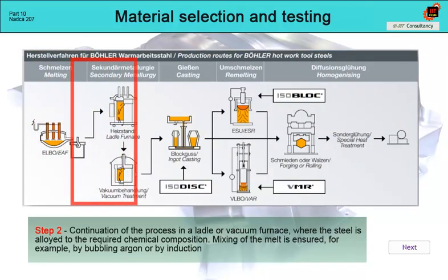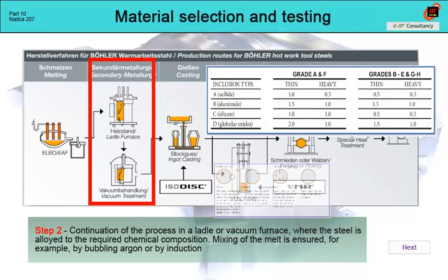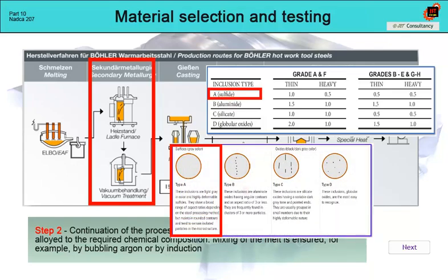In the next phase, the melt is processed in so-called secondary metallurgy furnaces, where the carbon content is reduced to the required limit, and the chemical composition of the steel is adjusted by adding some elements or reducing others. The result of this secondary melting process is steel with the required chemical composition, but it may contain a large amount of unwanted impurities in the form of non-metallic inclusions or globular oxides. Although the limits of these impurities are defined by standards, they are so wide that this steel can have very diverse properties, from the good to the bad.